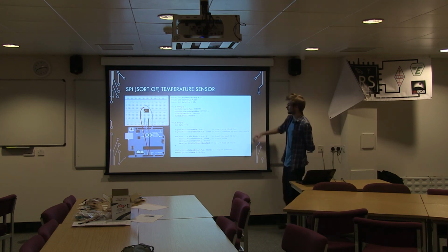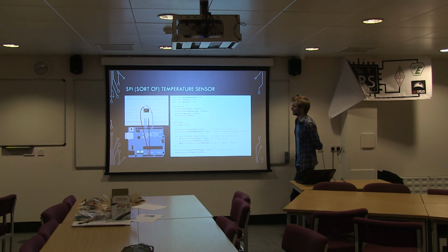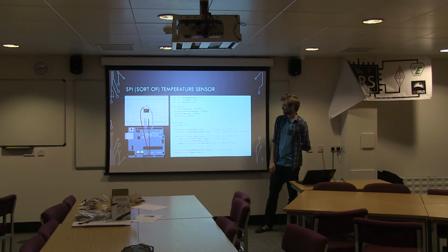So we've set up the clock pin, the slave select pin, and the data pin. That's just setting them up as our outputs and our input to read the data back in. Then literally through here, we're just using the digital write functionality in the loops you've seen before to implement the system that was shown on the previous slide.